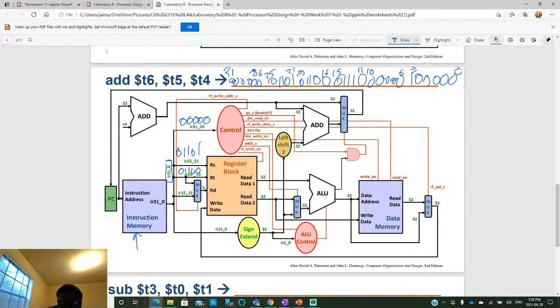Well, now notice that that input also goes into this mux. So remember when we talked about muxes? Yep, they have come back. So what I'm going to do is just apply some logic here so it makes sense. So you have that input here, and then 15 to 11, you have these bits, which is our D.